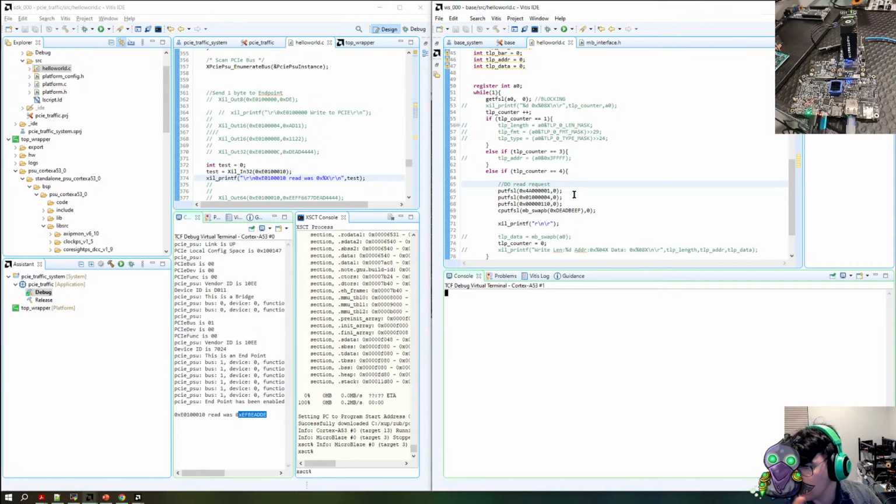So the Xil_In, okay, won't say 1, 2, 3. Yes, the putfsl is the MicroBlaze writing directly to the AXI stream. The Zynq Xil_In is basically an AXI memory command. And here, the Zynq as the root complex is reading a specific address that's associated with the PCIe.